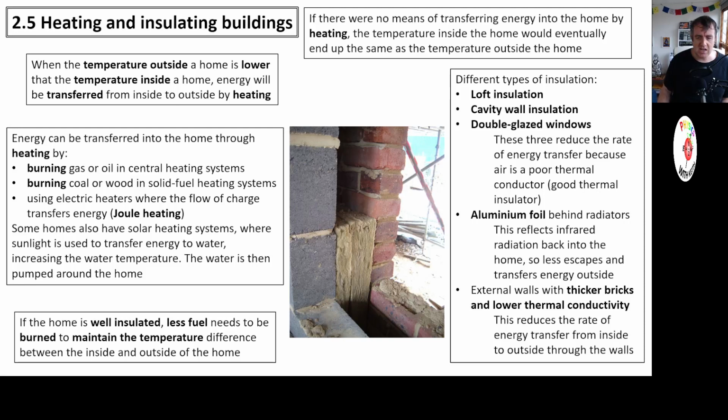So that's getting energy into your home. The better insulation that you've got, the less fuel needs to be burned or whatever to maintain the temperature inside. Now, what about in the summer? In the summer, we usually want to be cooler on the inside because it's hotter on the outside. And the energy is going to try to conduct into our home. Well, better insulation is going to help, yes.